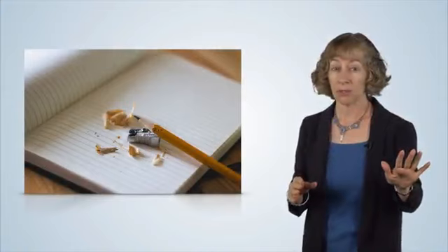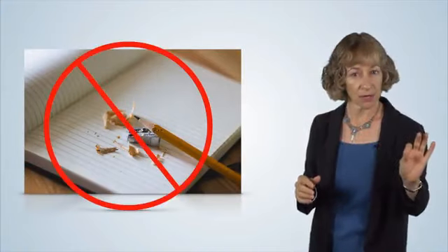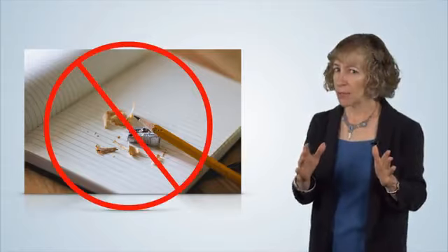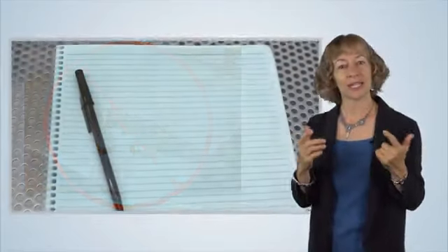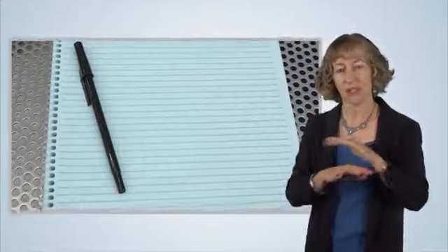There are also strict requirements regarding what is allowed in a clean room. For example, normal paper is prohibited because normal paper sheds a lot of particles. Likewise, pencils shed particles. So instead of typical paper and pencils, we use specialized clean room paper and pens that do not shed particles. Let's go into the clean room now and meet one of my students, and she and I will gown up and show you what it's like to enter the clean room.